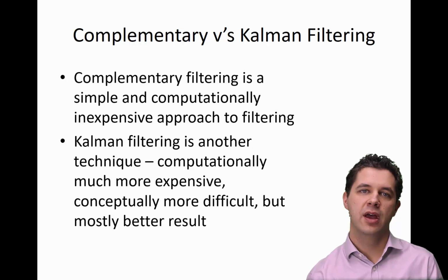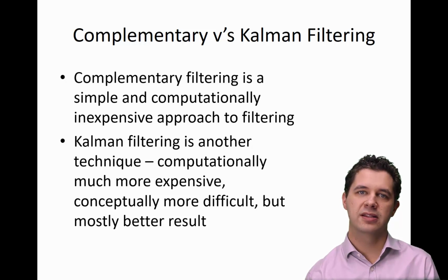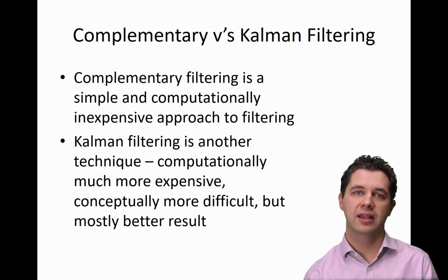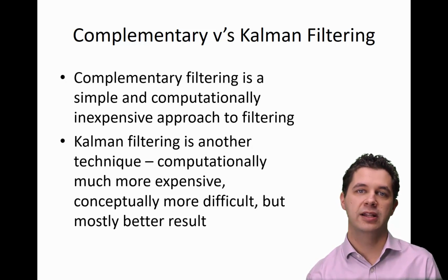If we're dealing with a mobile robot that's in a limited processing environment, we might go with a complementary, but if we can have MATLAB and other things available to us, and people typically use toolboxes and things like that to implement these sort of things, our Kalman filtering typically will give us a much cleaner option.